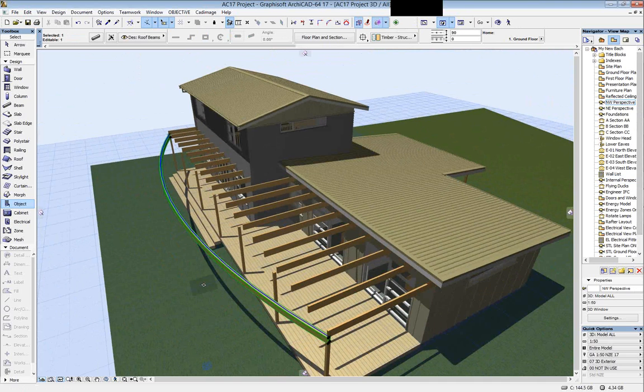But also we thought very nice, because of course the beam tool uses complex profiles, you can apply a shape to a curved surface now, natively in ArchiCAD, which is great. Bunch of different ways we thought that could be used. Say you've got a kidney-shaped swimming pool, you wanted to add an edge tile to it.